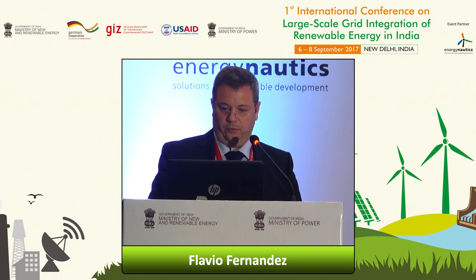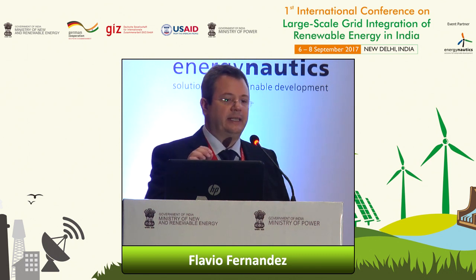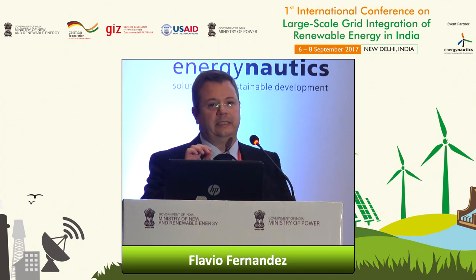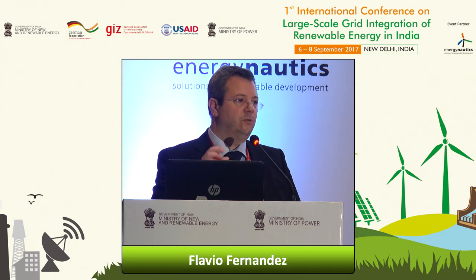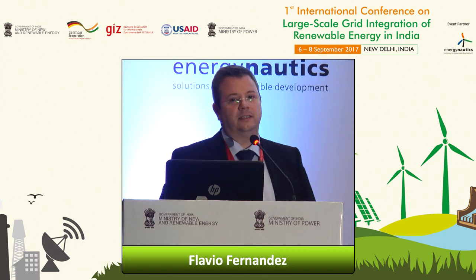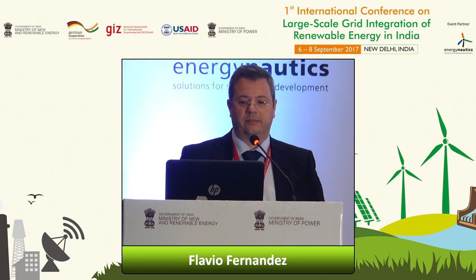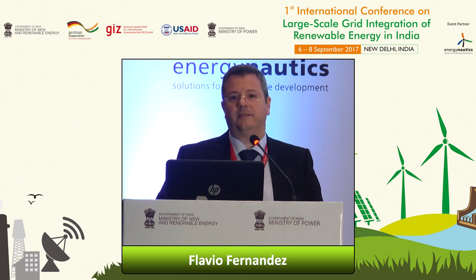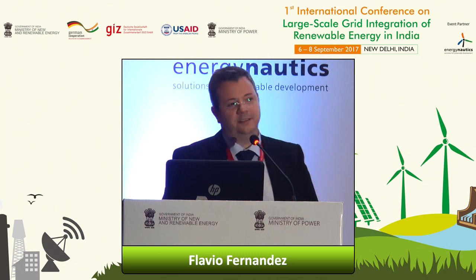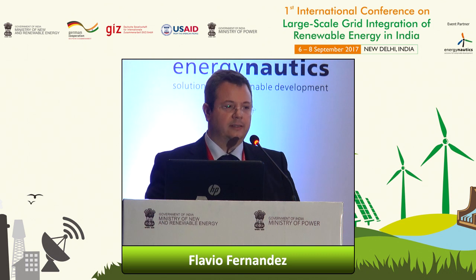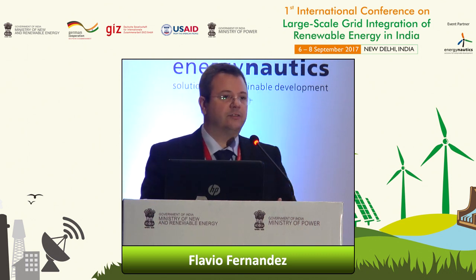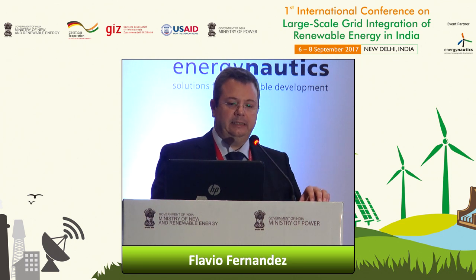And these are probably one of the most commonly used. So what is the main characteristic here? We are not talking about instantaneous values anymore, but about a fundamental frequency model. So we capture the behavior of the model at power frequency, and we neglect everything that is different from power frequency. So we cannot replicate different time constants or harmonics and so on. In general, you will have a positive sequence representation. This is what most of the solvers will do.